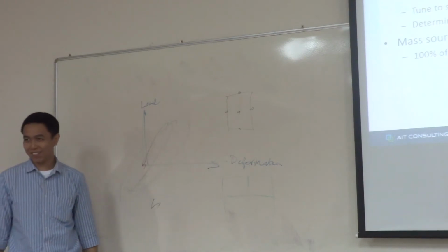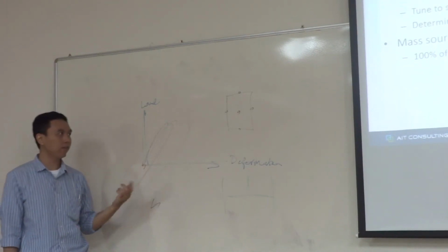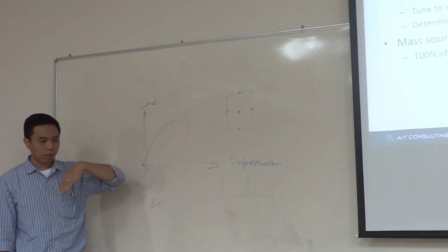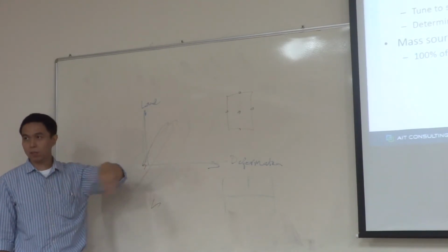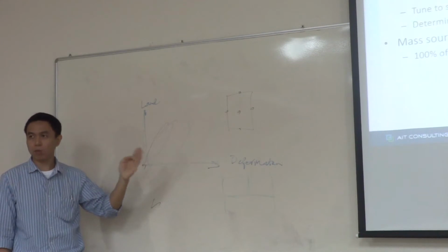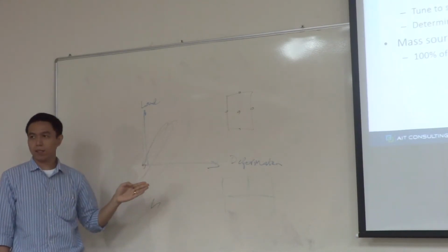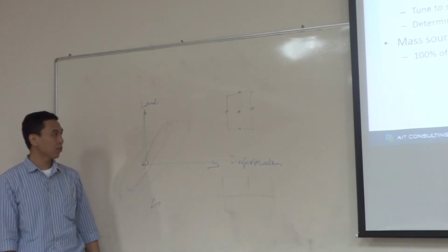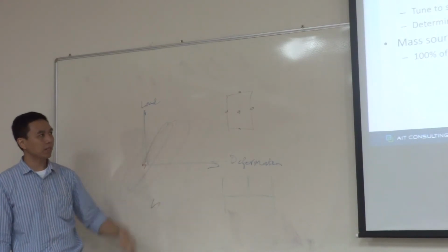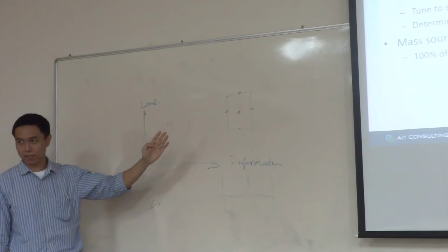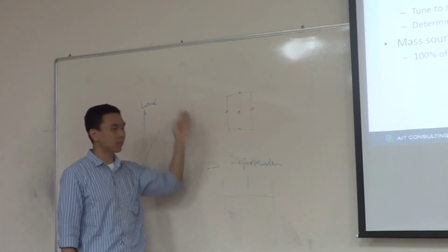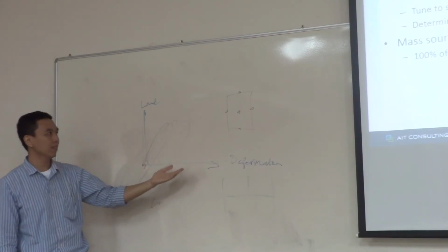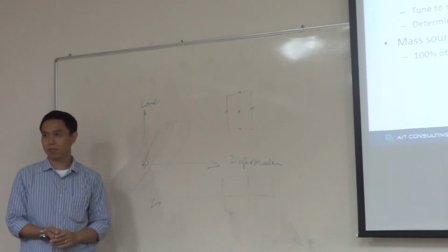In theory, if you apply the seismic force parallel to the principal direction of the building and design the building, that will be the conservative one. That will give you the maximum design force in the building. Okay. So, for example, for an L-shaped building, we have to find the principal direction first, and then apply the earthquake force in those two principal directions, and then check the design. This will give you the largest force that can occur in the members.